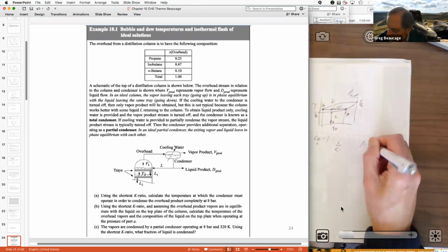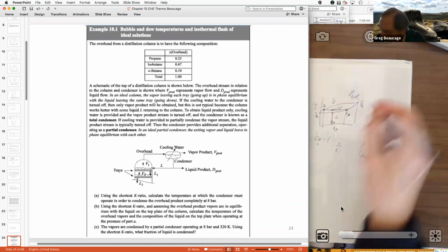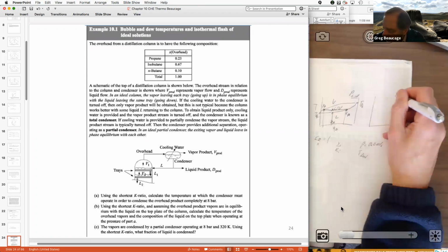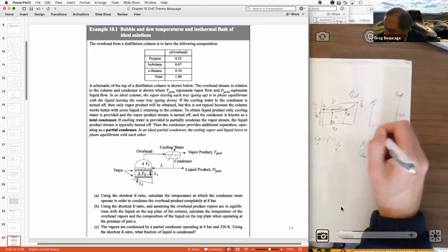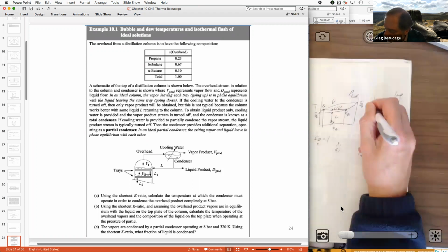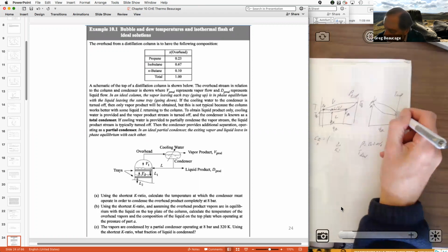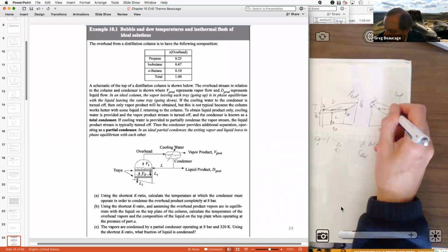And then you need to find the dew temperature. So it's this other plot. You want to find that T, but you can have the saturated pressures here. That's the saturated pressure of A, the saturated pressure of B. And it has kind of the same shape to it. And we're doing the same thing. We're starting in the middle, and it's going to separate out into these two. This is liquid and vapor.